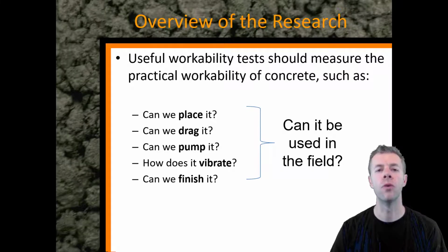Here's an overview of what we're trying to do. We want to use workability tests that measure practical concrete. Like, can we place it? Can we drag it? Can we pump it? Can we vibrate it? Can we finish it? Things that matter. Not things like the slump test, just how far it falls. How does it really perform and what we need our concrete to do? Can it be used in the field?